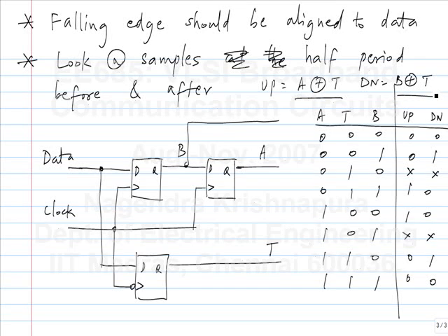Yeah, actually what you want to do is just see, the problem is A and B are aligned, meaning in their transitions. A and B are one symbol apart, whereas the transitions of T occur half a symbol apart. So you need to delay T by half a cycle. You don't need to delay B at all, right? So what do you do?